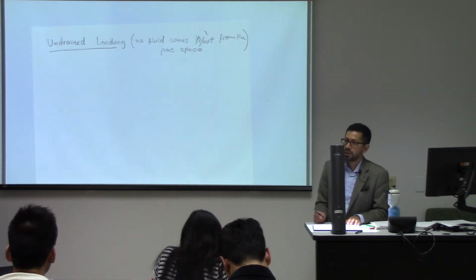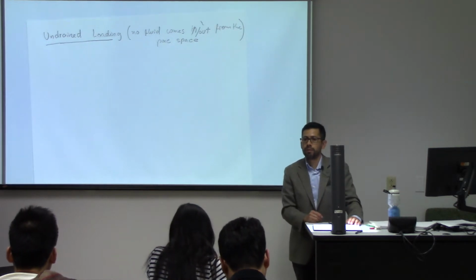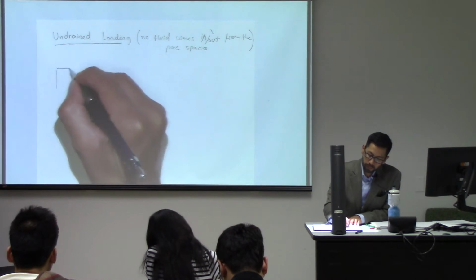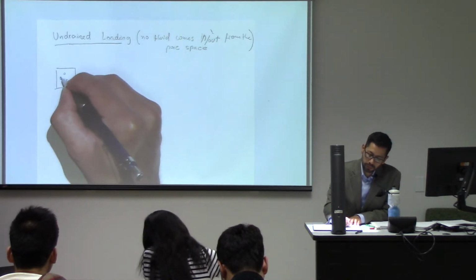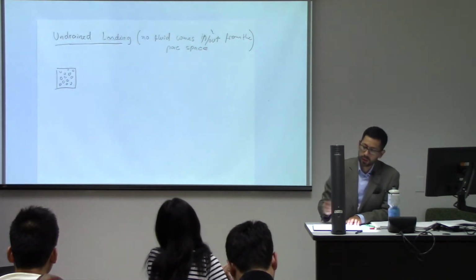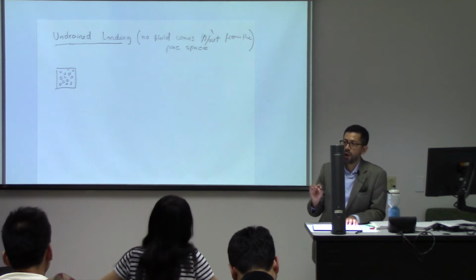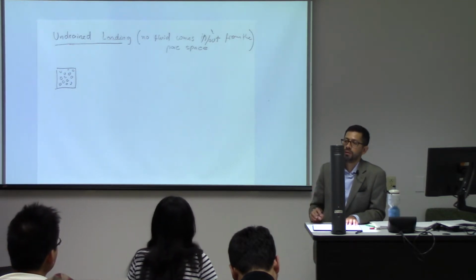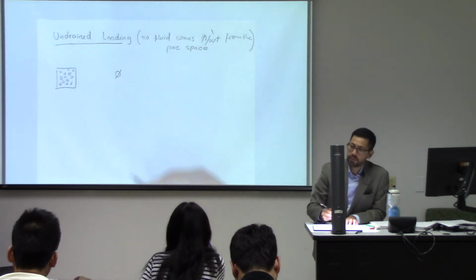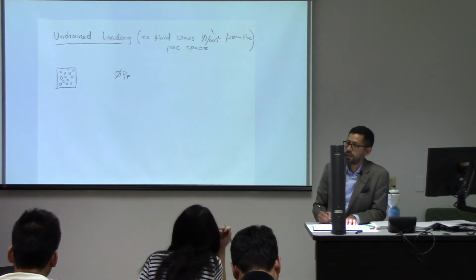What is the amount? If I told you, tell me how much mass per unit volume I have inside a porous medium, how much is that going to be? It's 1 minus the porosity times... No, I want fluid mass. Porosity times fluid density. That's it.